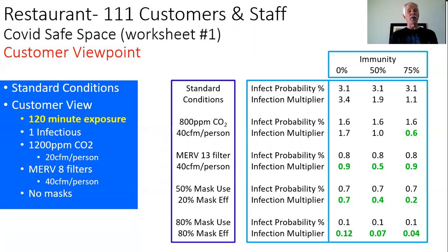And carbon dioxide is easily measurable and it's inexpensive to measure. About $200 to make this measurement if you don't have sensors in place already, and most of you do not. So standard ventilation would have you at about 1,200 parts per million. And standard air filtration, if you do have a recirculating air system that filters the air, most likely is a MERV 8 filter. And MERV 8 filters do not remove virus. You need MERV 11 or better.